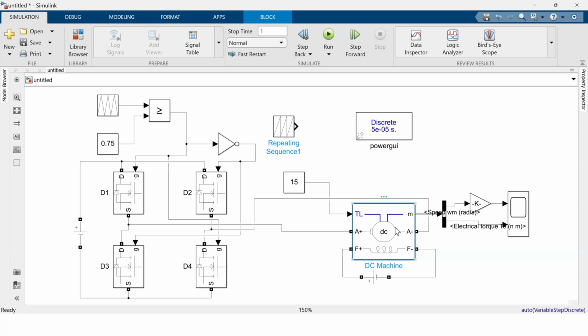Inside the block, you should know what is happening, how exactly the motor can be controlled. We are trying to explore and discuss in detail. Next time you should be very clear: this is the PWM generating method, this is how the PWM is going to change, and due to this change the motor is going to get a controlled output voltage. You should be very clear about this before developing the EV.